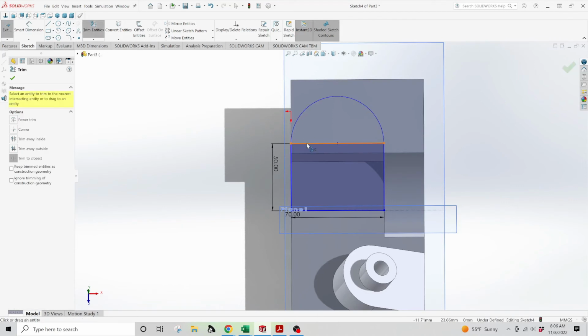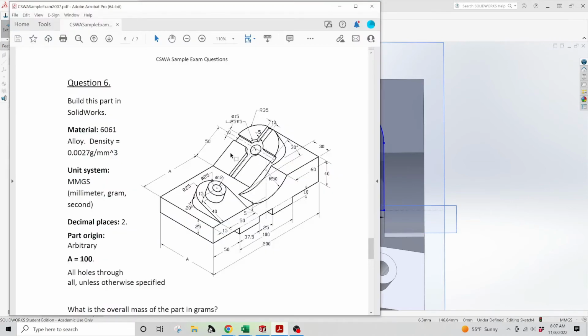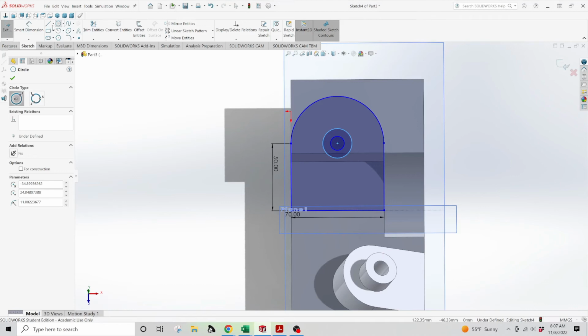So now we're going to trim this out because there are a couple of things that we need to do. There is still going to be the two circles. We have to get off the trim entities. So there is going to be the small inner circle and the large outer circle, and we're creating this geometry. Based on this, we're going to create just these two rectangles. Center points won't really help here. You really have to have left or corner rectangles for this.